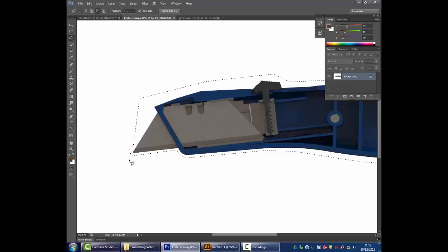this is actually quite hard to do because you've got to press Alt twice. So it knows it's negative, and then you click the mouse, and then you press Alt again, hold it down, and then you can have that polygonal lasso again. Takes a bit of getting used to, but it's quite handy. So you could go around and be a bit more precise.